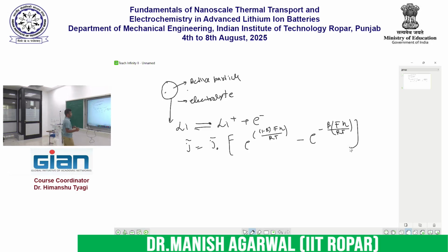Okay, now if it is positive, that means the current is flowing from the electrode to electrolyte, right? Or I can just say E, and this is either P or N. Okay, so if the current is positive, it means the current is flowing out of the active particles. Okay, and if it is negative, that means the current is inward, right?